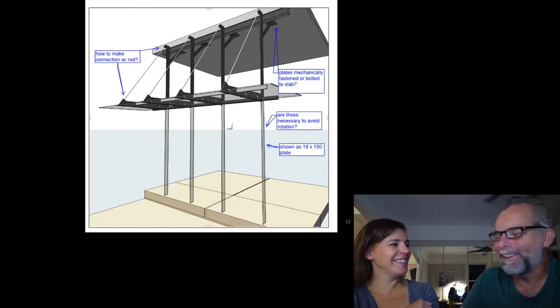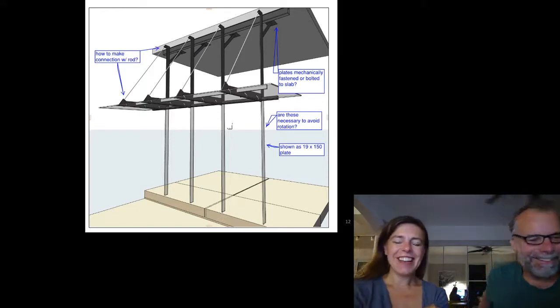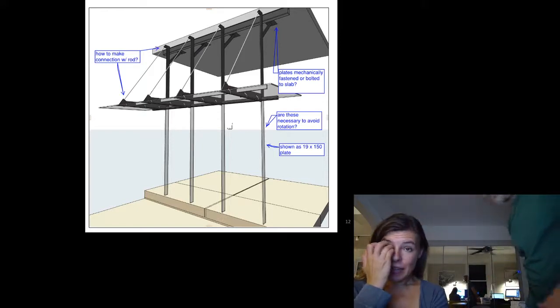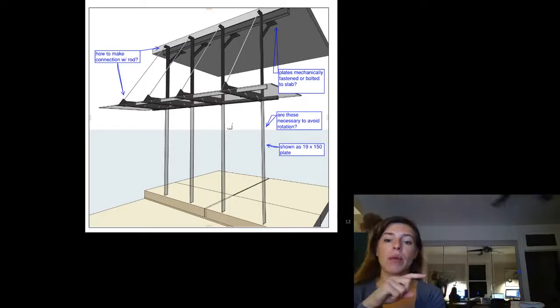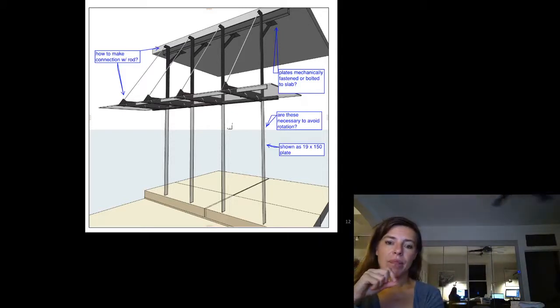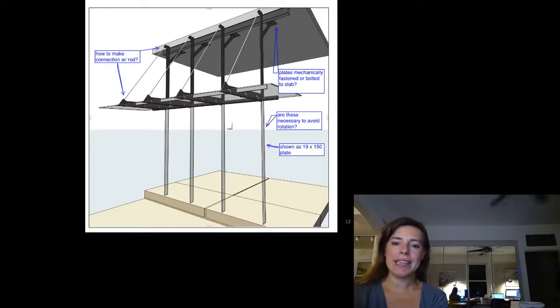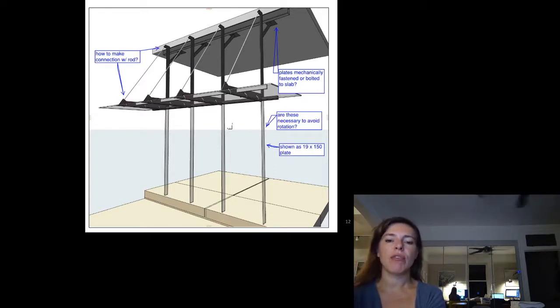Right. Yeah. It's funny, that's exactly why I was able to make that change on that project I was just talking about. They originally had a gravel system on top of the roof. They made an architectural change to get rid of that ballast, so now my wind load governed more than it did, and once it governed more than it did, I didn't need those tension rods anymore.